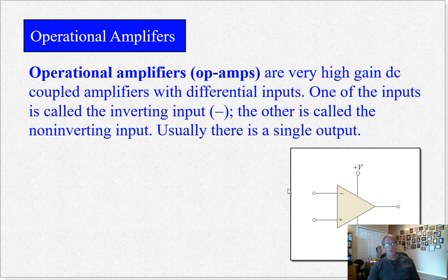The important thing to remember, and we'll go over this again, is that it is an amplifier. What does it amplify? Well, it amplifies the input to create the output. There are two inputs. Does it amplify one input or the other? No, it amplifies both. Actually, what it does is amplify the difference between the inputs. So if this amplifier had a gain of 2, and you put 1 volt difference between these two terminals, in other words, 1 volt on the plus and ground on the minus, you would get 2 volts on the output because it's a gain of 2.